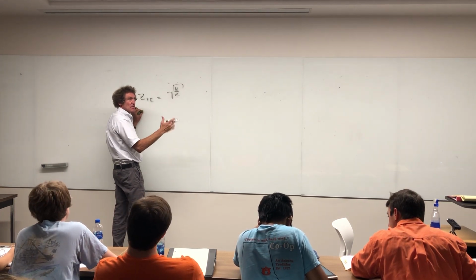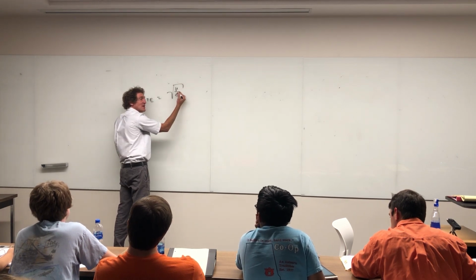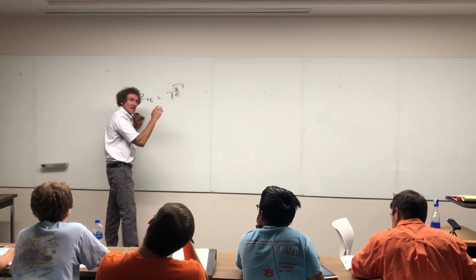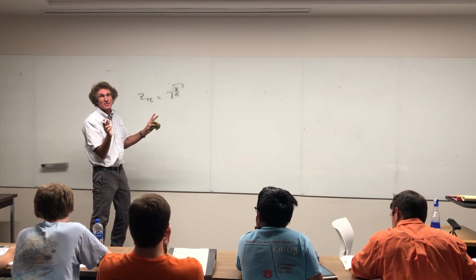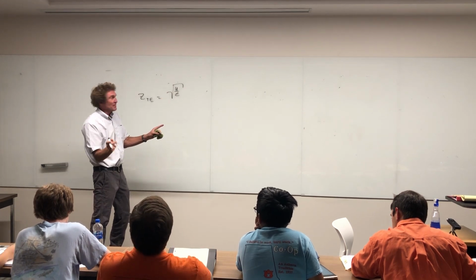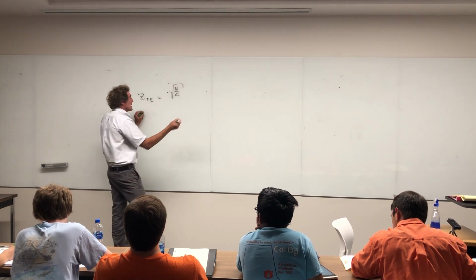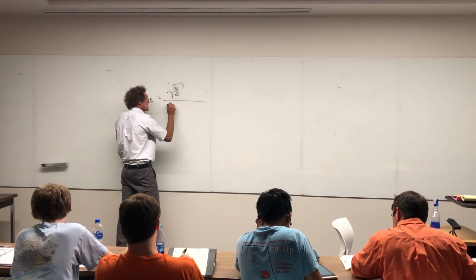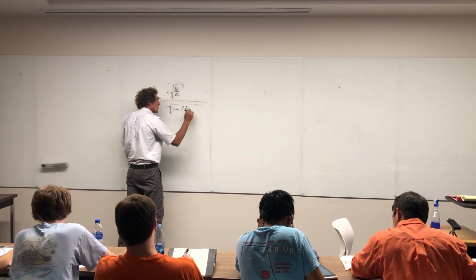The mu and epsilon of the material in the guide, the dielectric. Usually if mu relative is not equal to 1, and mu naught is not equal to 4 pi times 10 to the minus 7, there's something very odd going on. They might have a material that actually has a filtering property, but I've never ever seen where mu isn't just plain old mu naught. Now epsilon will change values. Then you divide this by the square root of 1 minus (FC over F) squared.